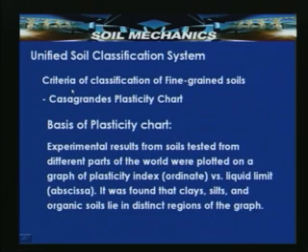The criteria for the classification of fine grained soils is entirely based on the plasticity chart. This was also developed by Casagrande, as part of the Unified Soil Classification System for classifying fine grained soils. The basis of origin of this plasticity chart is the correlation of a number of soil properties collected from throughout the world.